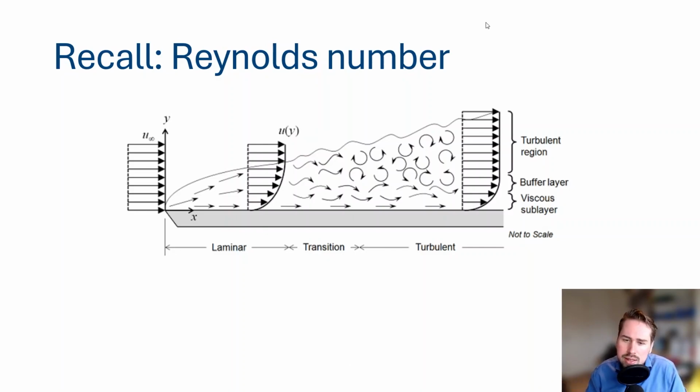For a very high Reynolds number, we have a turbulent flow, and this is very good for heat transfer, since all the particles are tumbling over each other, it's very easy to exchange the energy with our borehole and with our ground. So this is typically the region you want for your system, although it has a higher pressure drop and hence also a higher pump consumption.